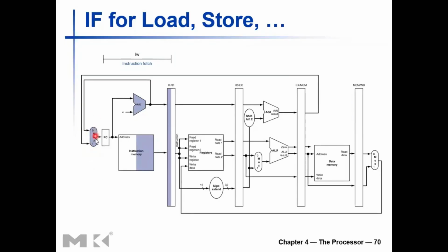Actually, it's not very correct to shade this multiplexer in this diagram, because the multiplexer is actually used, or consumes time, in the memory access stage, but the result is needed just to make sure that the value is already propagated. So you don't really need to have the multiplexer shaded here. Adder is used in this clock cycle. Instruction memory is read in this clock cycle.